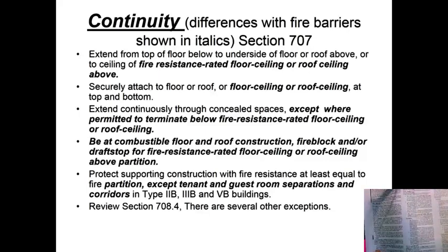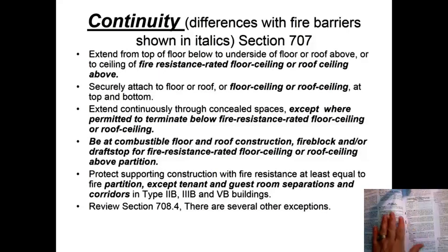A lot of times you've got to go back and forth to be able to look at these. So let's go back to fire barriers, because it's real important to look at that. It says enclosures for exit access stair. It gives you the rating, and it's telling you to go to section 1009.3.1.